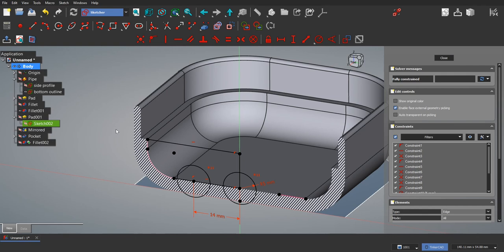That's why if I'm modeling something for myself and not trying to be super fast about it, but rather I want a good, strong model, I will oftentimes use expressions, or this version of FreeCAD has spreadsheets where you can essentially put all of your dimensions and all your variables in just an Excel spreadsheet.